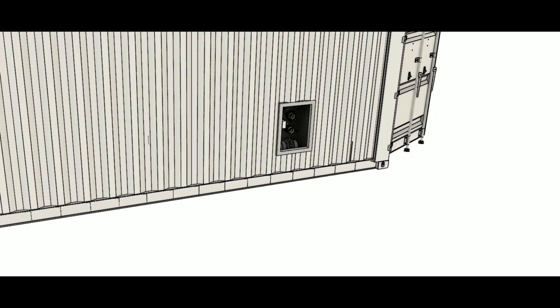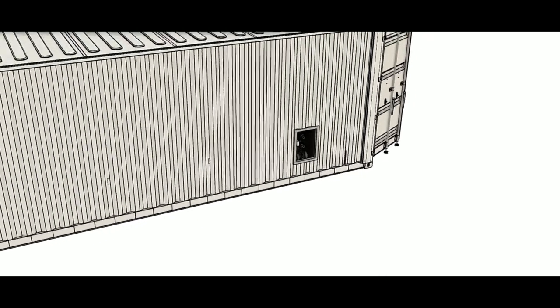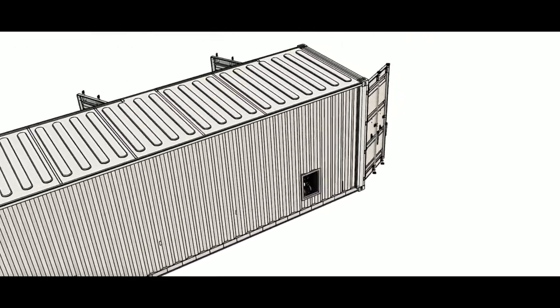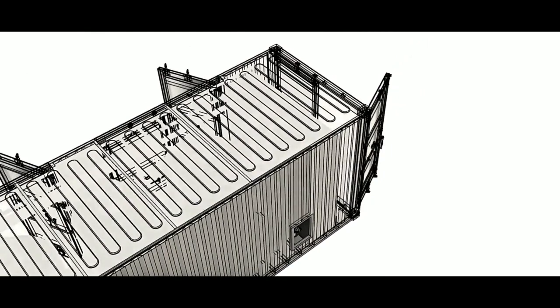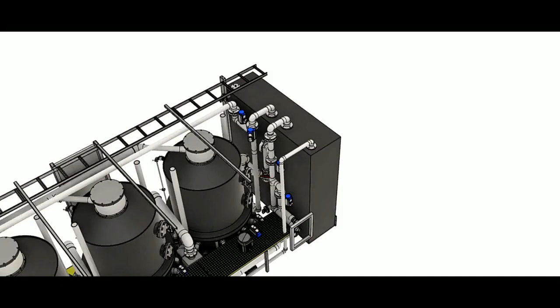We can just return any overflow that comes into the system. If we move up and we sort of peel away the skin a little bit, you'll see that it's some fairly clever engineering in the way we've compacted it all into a relatively tight space. On the right-hand side, you can see the influent tank. That's a 3,000 litre tank. Each of the primary fractionators runs in about a 2,600 litre batch.